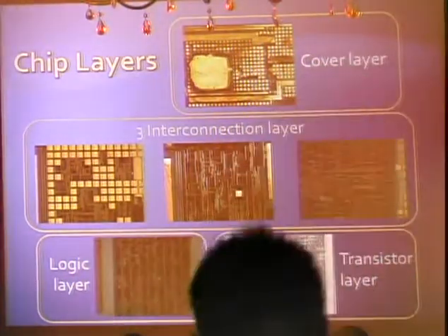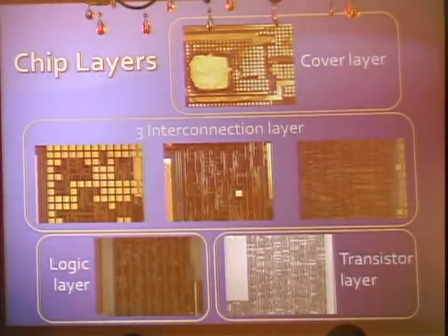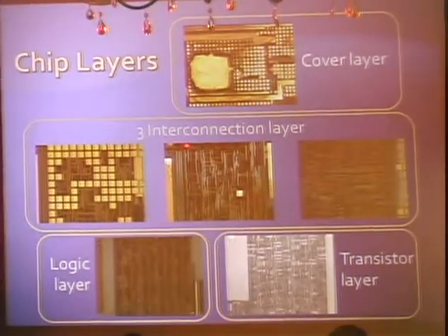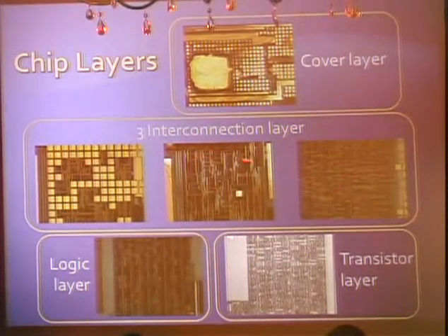And then the last layer has no practical functionality other than connecting to antennas, but it does have some visual protection. So you couldn't have done what we have done without opening the chip, since the last layer prevents you from looking into it, where the rest of the chip is really just glass. So you can maybe see that the lower layer, for example, the horizontal line here, shines through to this layer where it's all vertical, right? Yeah, silicon oxide, all glass.